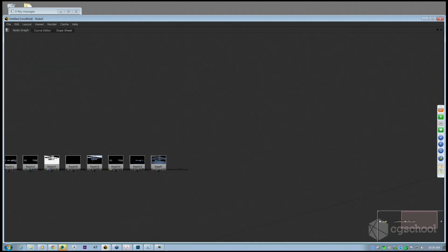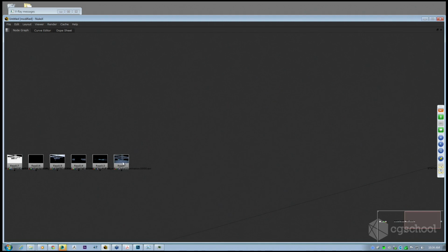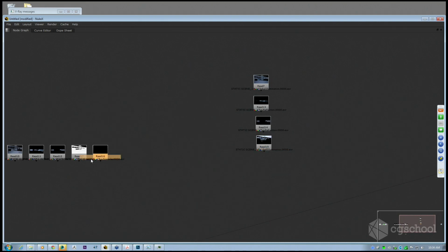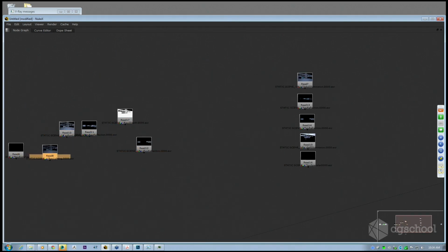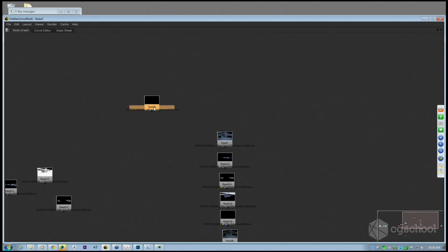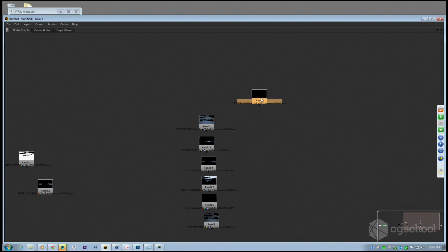So basically, there are a few passes you need to rebuild your RGB. You need global illumination, so we'll put that over there. You need your V-Ray reflection, your V-Ray refraction, self-illumination if you've got self-illuminated objects, so it's just being aware of what you've got in your scene, specular, lighting, and background if you have a separate background in your scene that isn't part of your lighting setup.